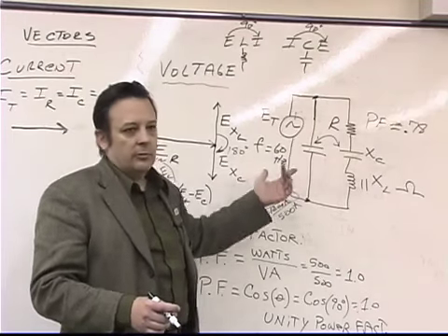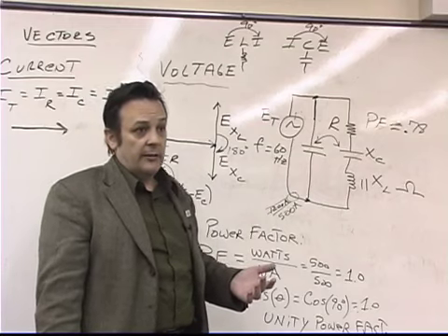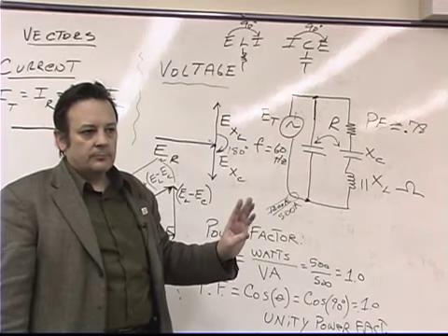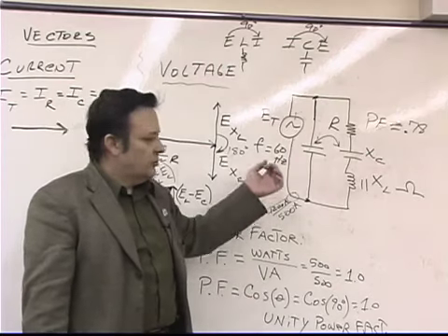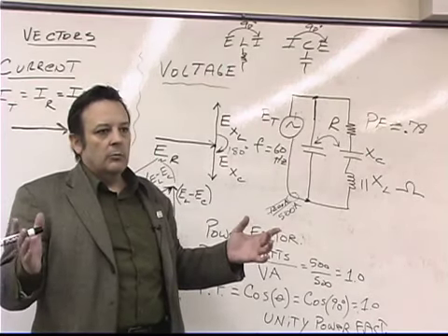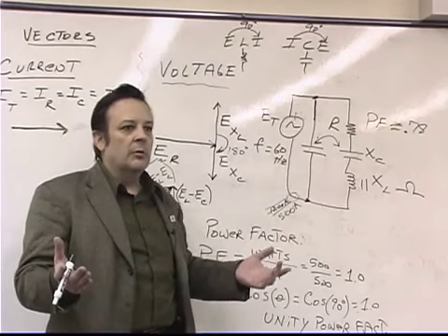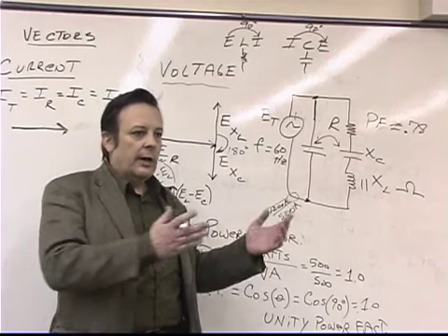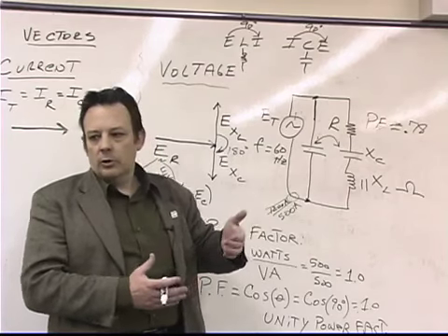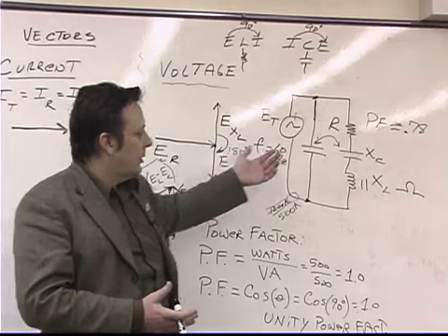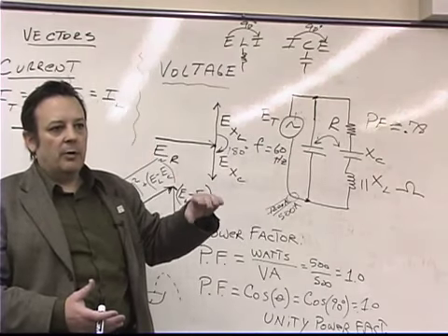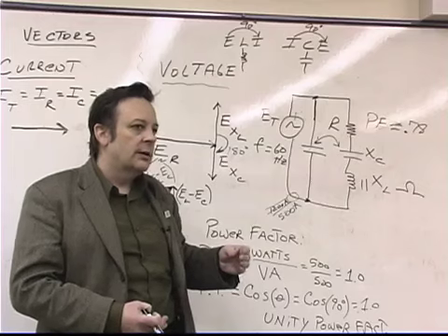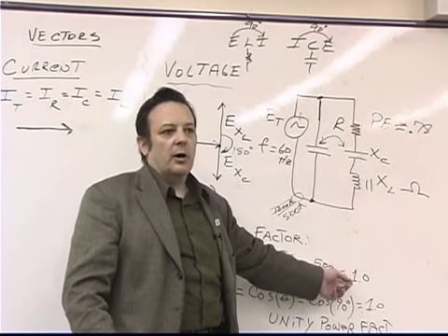So there are a lot of electrical engineering contractors and also electricians that have their C10 license that get into this business exclusively, where all they're doing is coming into the building, measuring and documenting how much power they're drawing when everything's on in the building and when there's minimal lighting and security systems on in the evening when everybody's gone home. Figuring out what the monthly bills are, or looking historically at what the monthly bills have been, and then doing a power factor analysis to figure out what the power factor currently is during high peak loading, and then what it would cost to get the power factor as close to unity as possible.